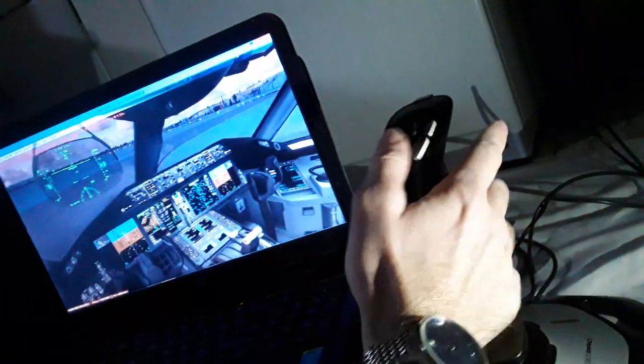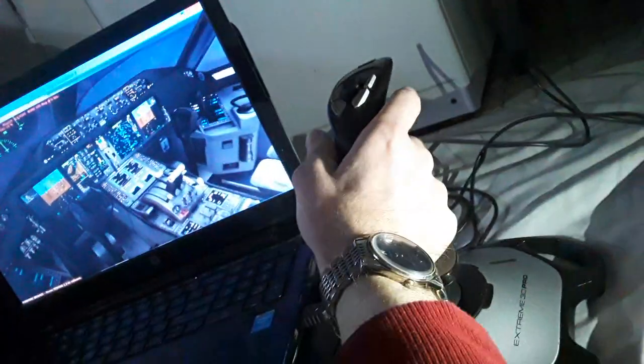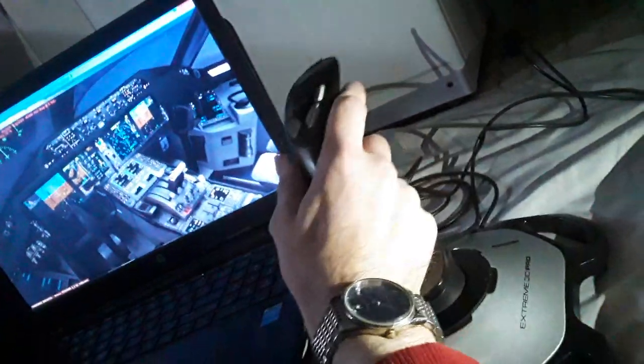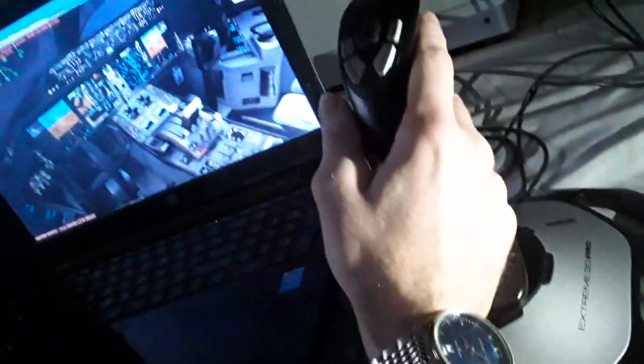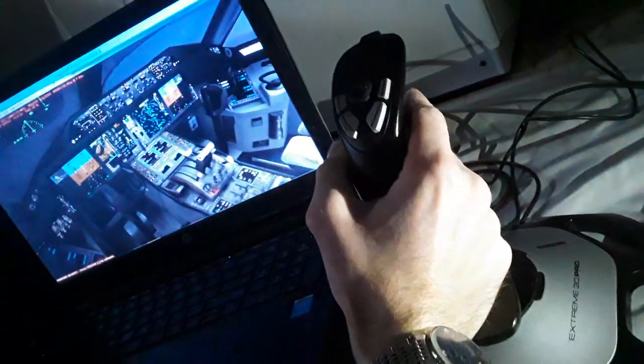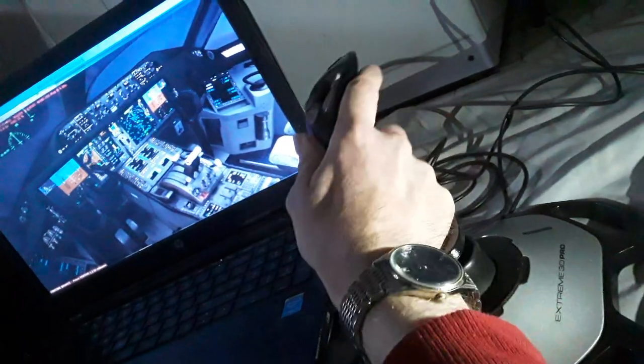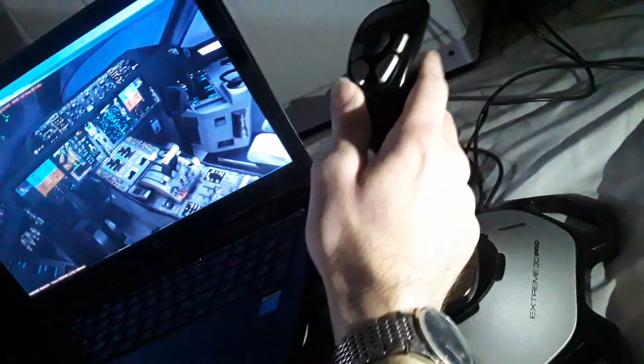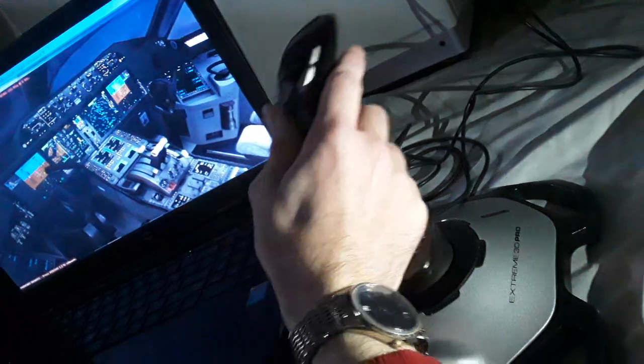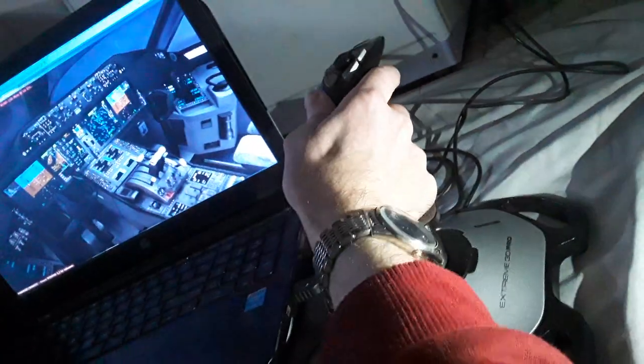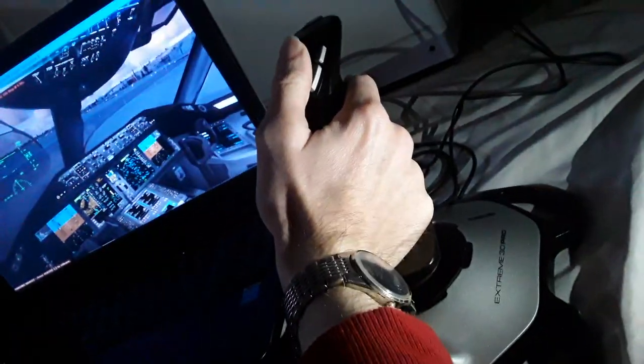So we have all flight controls like this. You can see again left and right side both move together, side stick deflection proportional to the yoke, climb, descend, make turns to the left, make turns in the roll axis, left and right, and the pitch axis, climb and descent, the elevator.